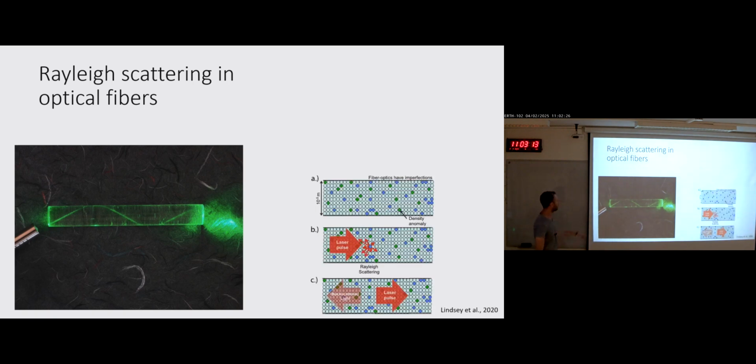Now, the reason that some of the light exits here, and the actual reason we can see this beam of light, is because the photons emitted into the fiber interact with various heterogeneities inside the fiber. The fiber is silica, but it has various anomalies, in density and material. And when the photons enter the fiber, some of them interact with these anomalies, and they are backscattered towards the light source. The reason that we see this light beam is because these photons are scattered back into the camera.